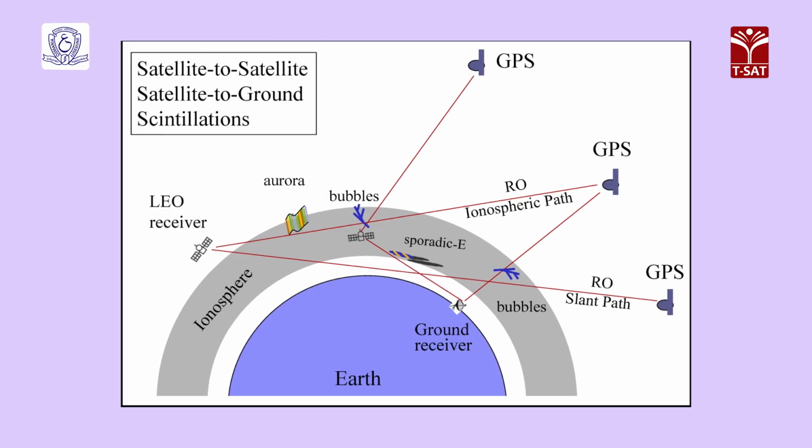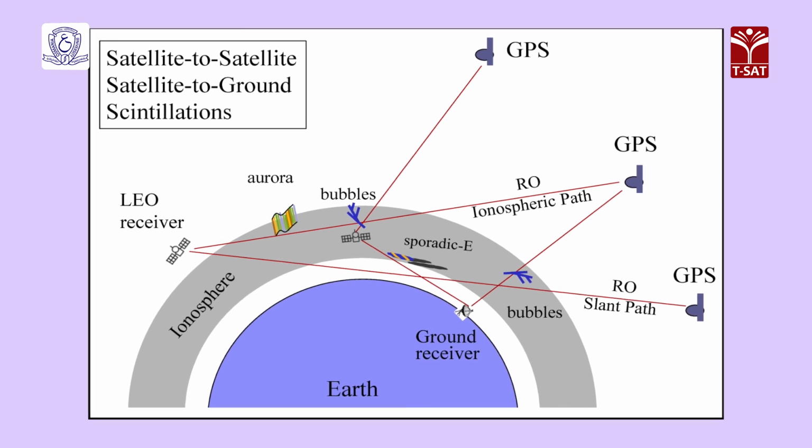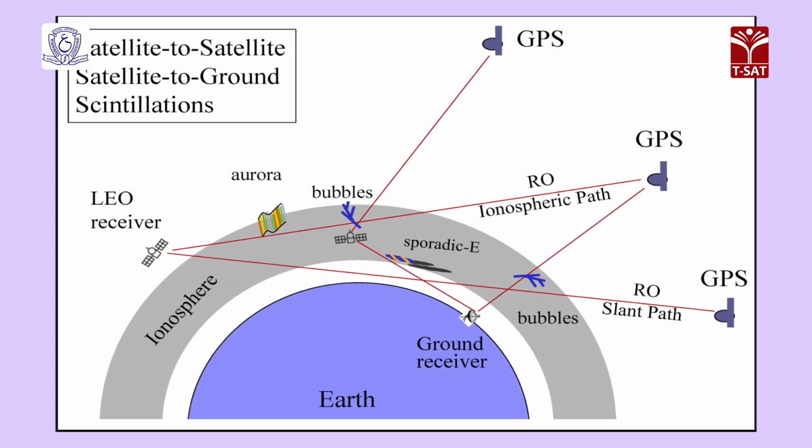Step 5. Correcting errors. So far, the calculations we are pointing to in GPS are as if the whole thing was happening in a vacuum. But in reality there are a lot of things which can disrupt the GPS signals. To get accurate results, these errors need to be corrected. For example, the ionosphere and atmosphere may be a reason for delaying the whole function. Some errors can be factored out by using arithmetic calculation and models. The relative position of the satellites in the sky can give rise to other errors.